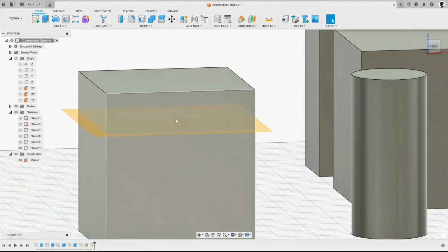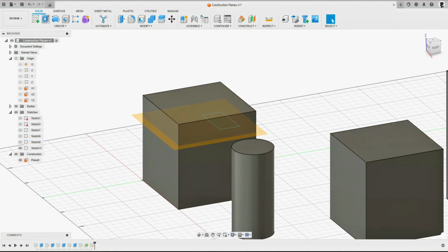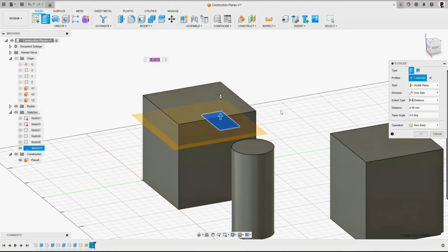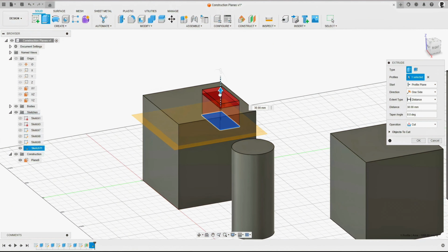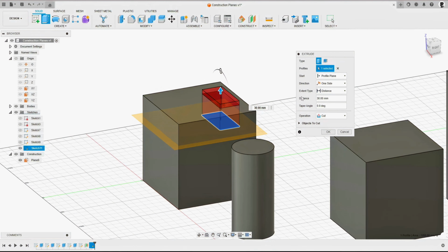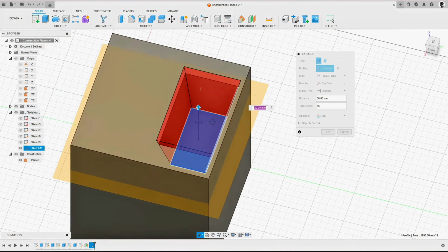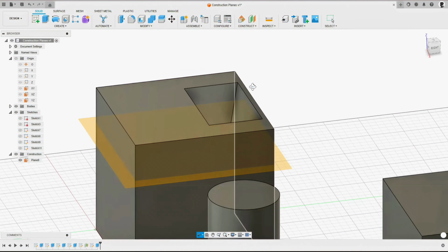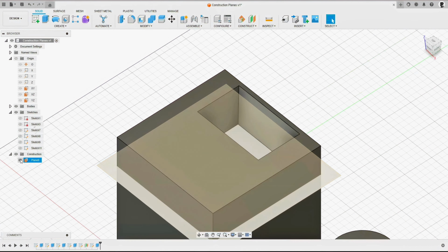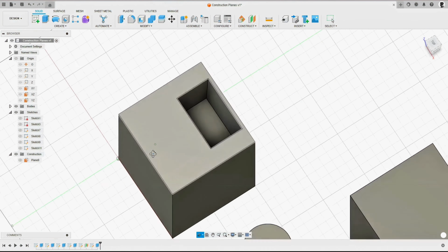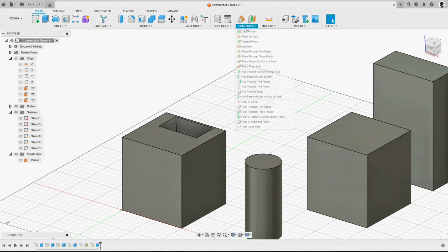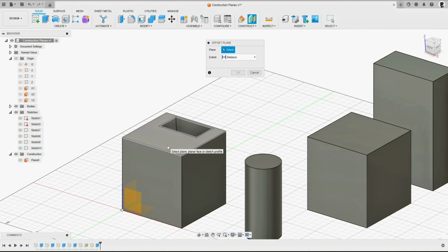So we see the sketch just there. Let's now go ahead on Solid, and I'm going to make an extrusion there. I'm going to draw the arrow up, and Fusion will recognize that as a cutting operation. So I'll leave that there for now. And I'll come across and input a taper. Let's go 15 degrees. Okay, and we see that tapering extrusion cut moving out there. If I press OK, we've now got that feature added. Move that plane. So that's how we add the offset plane. Nice and simple. Just select the face, select this position, and then we can begin sketching.